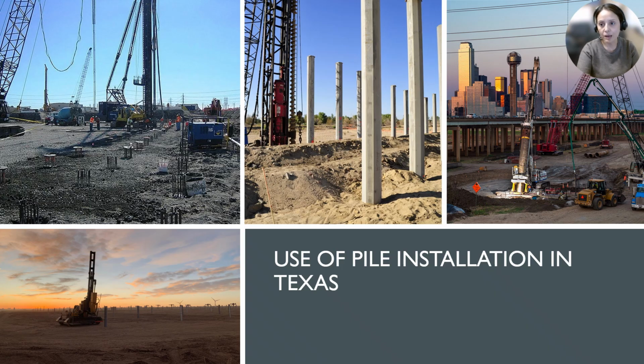Texas is a great example of how piles adapt to local conditions. For bridges and highways, driven piles, steel or concrete, are common. In Houston and the Gulf Coast, where clays are soft and water tables are high, drilled shafts are the standard choice. Out west, in renewable energy projects like wind farms and solar fields, we see a lot of screw piles and drilled piers. And in cities like Dallas and Houston, skyscrapers depend on deep drilled shafts to deal with expansive clay soils. In the next slide, I'll specifically cover the installation process for solar.